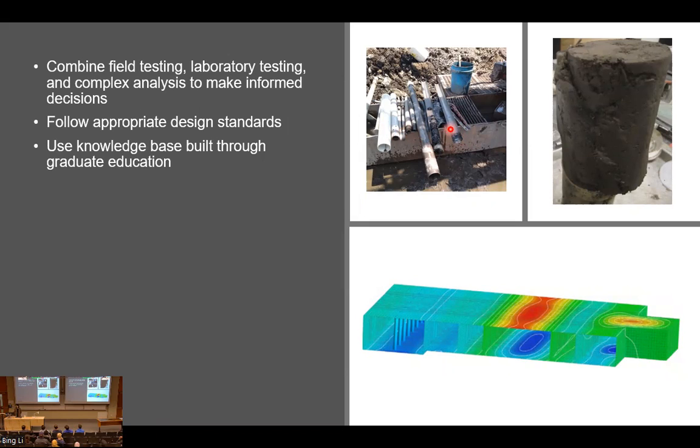So as a geotechnical consultant, you had to make decisions on what type of samplers and equipment to use in the field to get the best information possible. You also had to make decisions on how many boreholes you want at the site, where to make these boreholes, and how deep they should go to get the information you need to proceed with design.